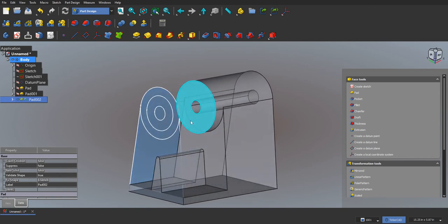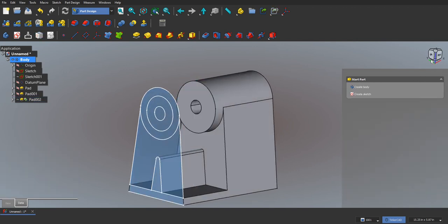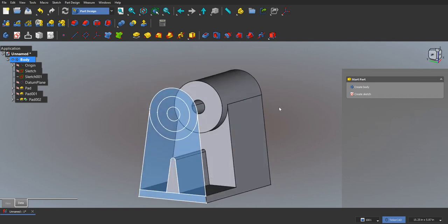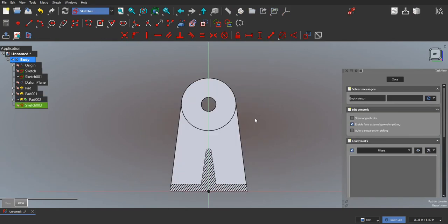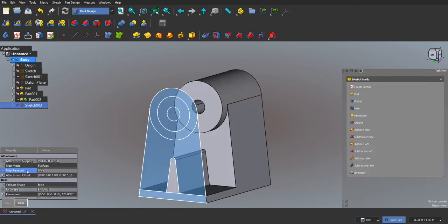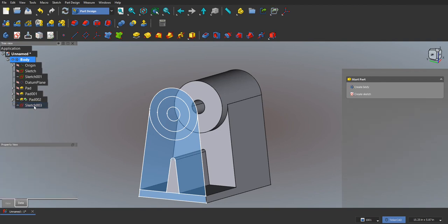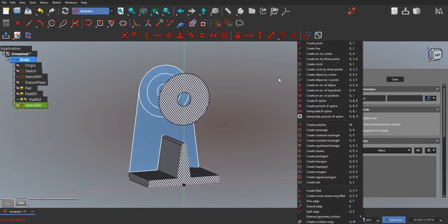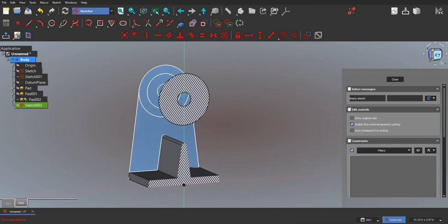So that's reversed. It's flipped around. We rotate around this way, so it's flipped. So we can still create a sketch. However, basically we need to actually exit and then say map reversed. And now when we look at that sketch, we're looking at the right view over here.